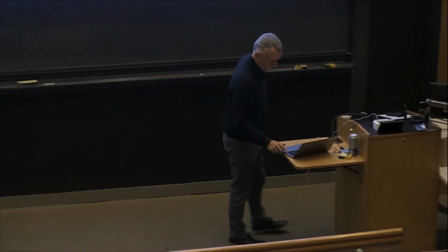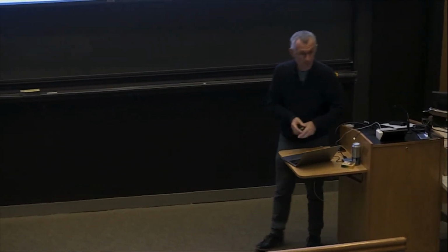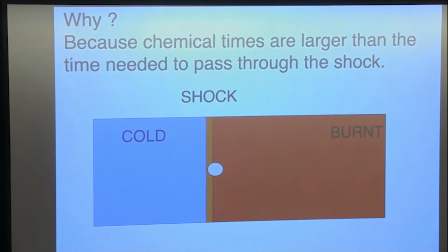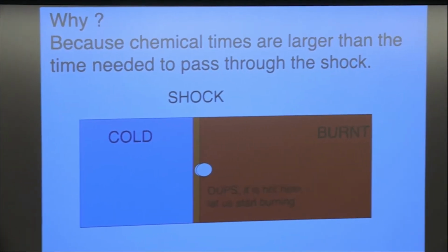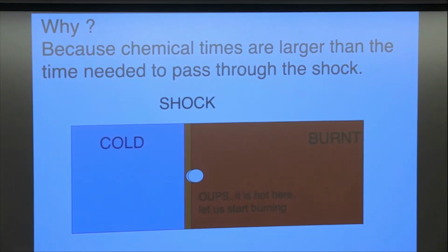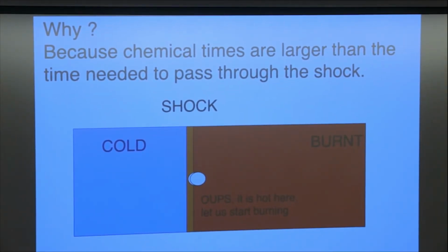Let me show you this picture. So you are in the cold gases. Bam, you hit the shock first. Through a shock, your temperature goes up. And then suddenly you say, whoa, it's hot here, okay? Chemistry has not started yet because a shock is only a few mean free paths. There's no time for chemistry to take off. But now that you're in the burned gases, you say, oh, it's hot, so you start burning. And then there's a flame afterwards. So you see it's a shock followed by a flame.